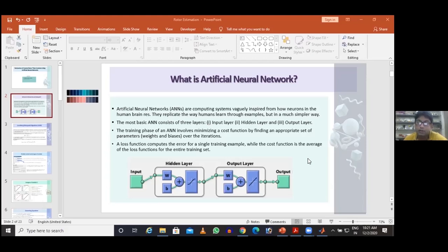The classical analytical concept may not always work, because some things are dynamic in nature, random in nature. So in all those cases, we need dynamic learning of the system parameters, and it is to be updated dynamically to compensate for the change of some passive parameters of the machine, to maintain the desired dynamic response of the prime mover.